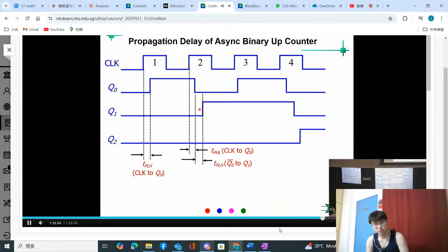And you can see that if you do a counter, you want to count them together. For example, I count 0, 0, 0, 0, 0, 1, and then 0, 1, 0. Now this time I cannot use it for counting. I have to count starting from here. 0, 1, 0 starts from here rather than from here, which is not at the clock edge.